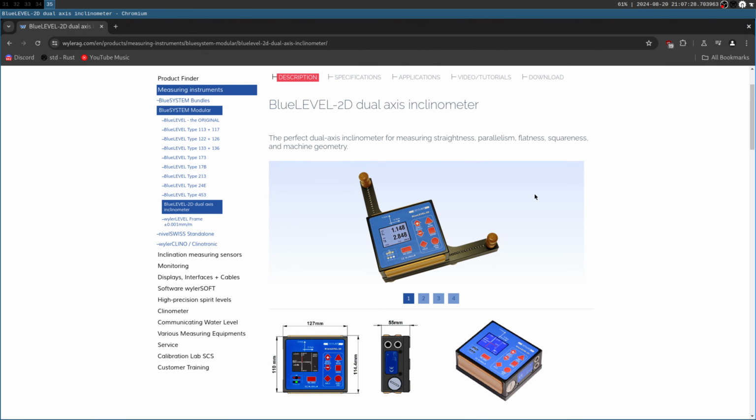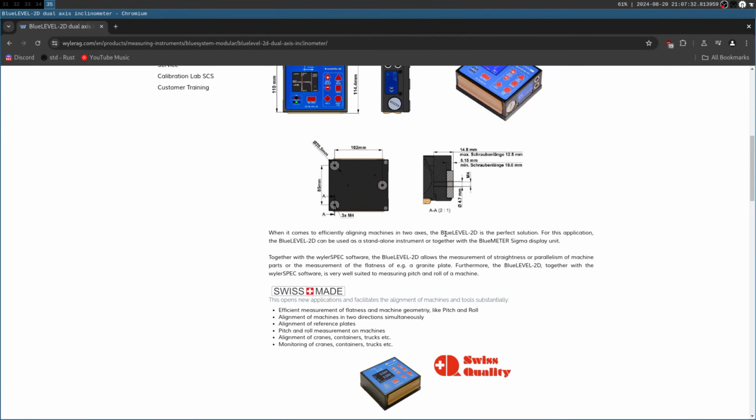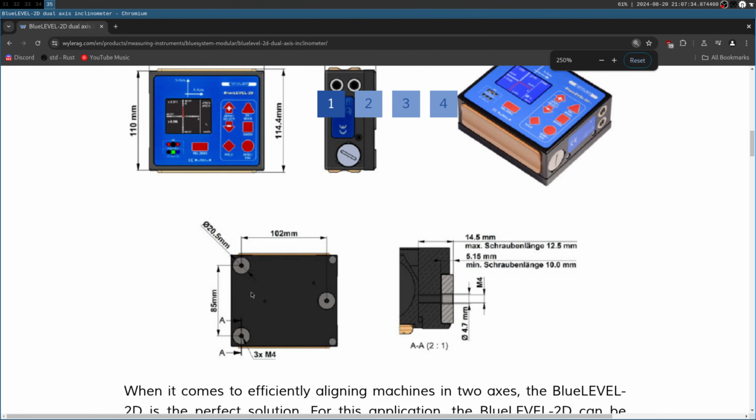This is absurd. Because if you think about 1 micron per meter, I can make an arbitrarily sized base for this. This has 3 sintered carbide feet for the base that are lapped flat. That's a really common thing. When you're making precision instruments, you want them to rest on 3 feet, not 4, because that guarantees you have 3 bearing points on a flat plane.